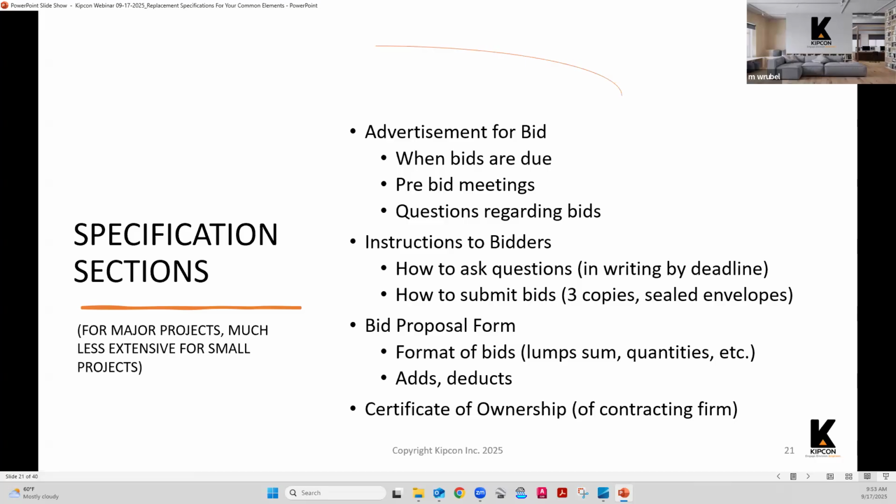We don't just simply say, here are the specs, give us your best price in a lump sum form. All the contractors get the same bid form and they're asked to submit their bid in that form, where the stages of the project are broken down. Using the pavement as an example, the stages might be their general setup as a beginning, any kind of traffic control, notice to tenants, and general mobilization. We'll ask for separate line items for that.